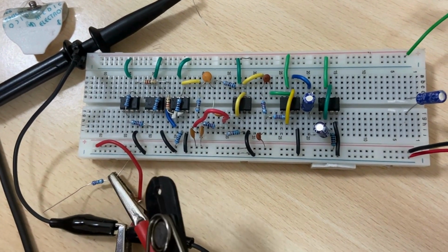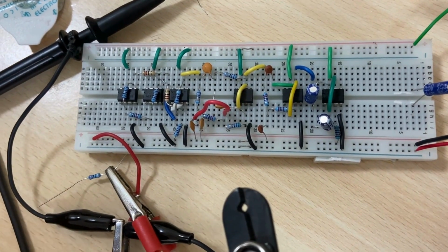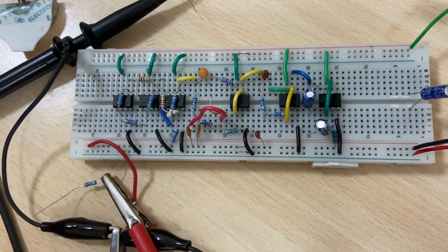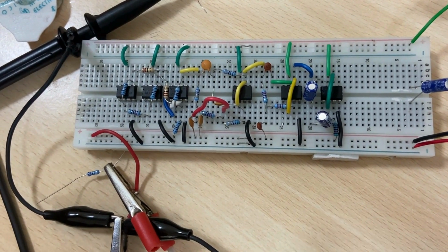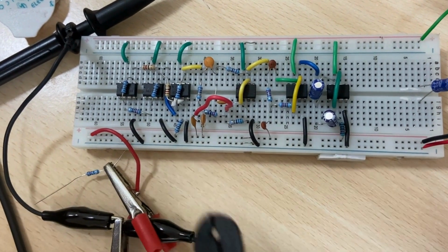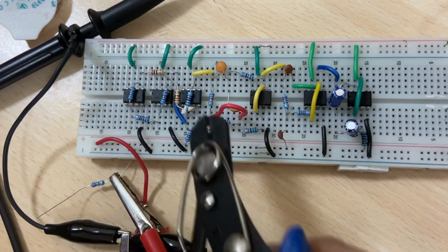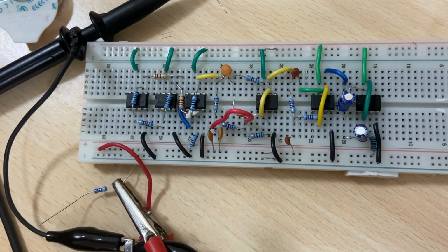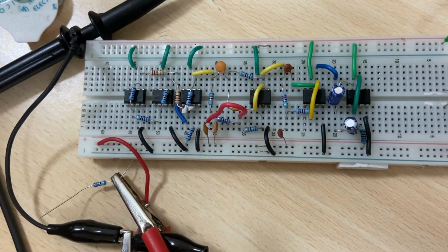The main function of this is to amplify the biosignals, which are in a very low voltage range, from 0.5 millivolt to 5 millivolt, up to 1,000 times, approximately 1,000 times, to a usable level. In our current implementation, we have a gain of around 800. The next stage is a notch filter. The notch filter cancels out the 50 Hz frequency coming from the AC signal, which is used in India.